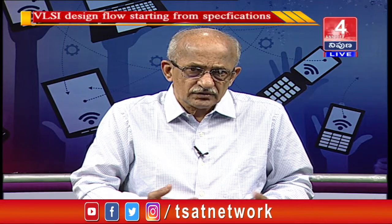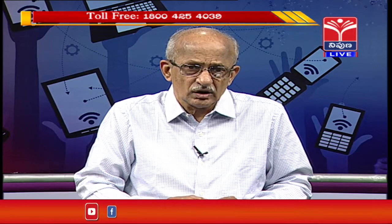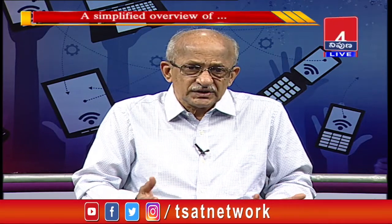4 states are there. From each state, either you can remain in that state or you can go to 3 other states. So ideally speaking, not just 3 transitions but 4 transitions, because a particular state can remain in that condition for a long time. Therefore, there are 16 possible transitions, but your state machine may not have all the 16, because your state machine has a certain job to do and your state transitions are there according to that functionality. So not all 16 transitions may get covered.